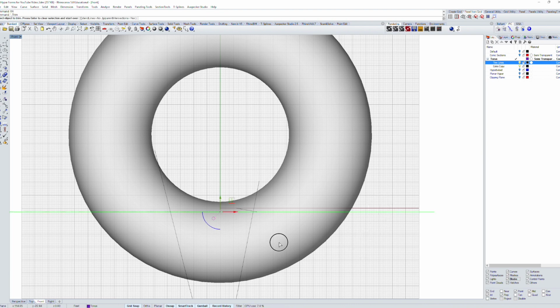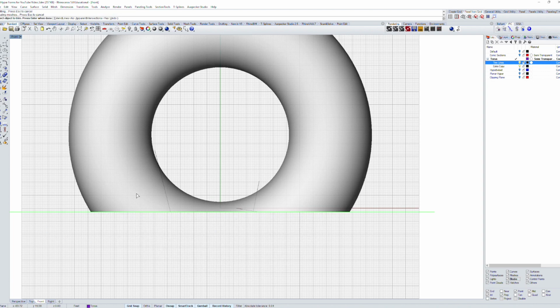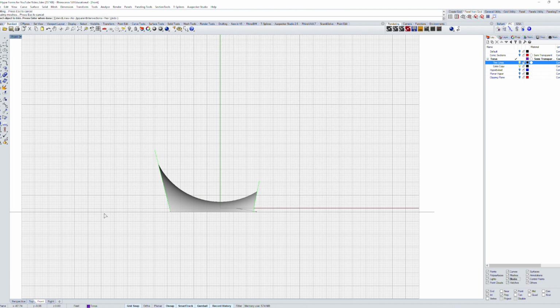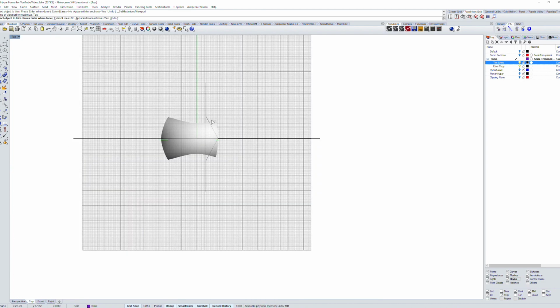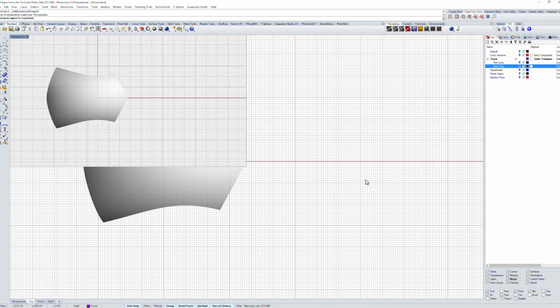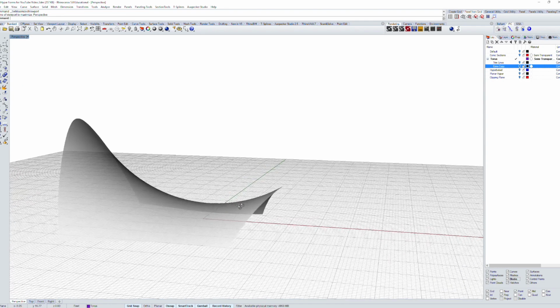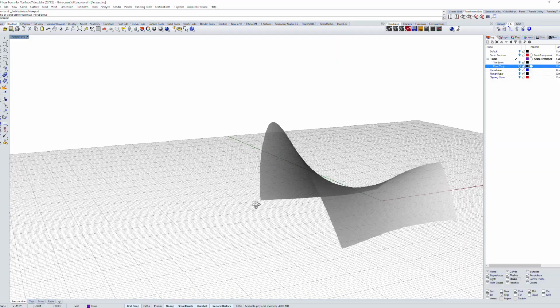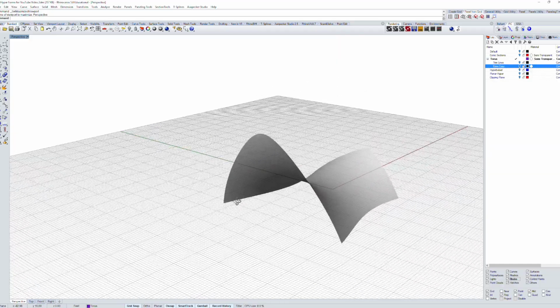and I'm going to trim everything down below. And I've got these two inclined lines, and I'm going to trim off everything above. Now, from a top view, I have two additional lines, and I'm going to use those to trim off these edges here. And now turn off that layer Trim Lines, go back to my form, and now I've got another form of a hyperbolic paraboloid.